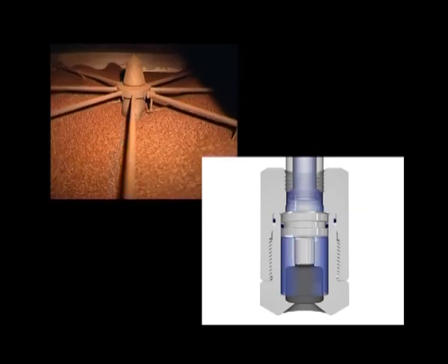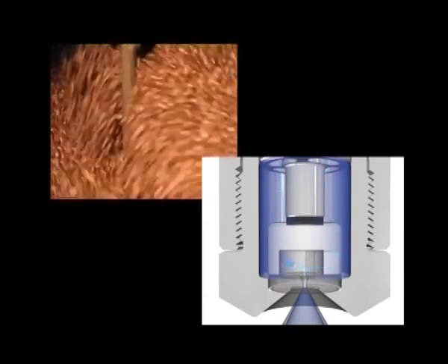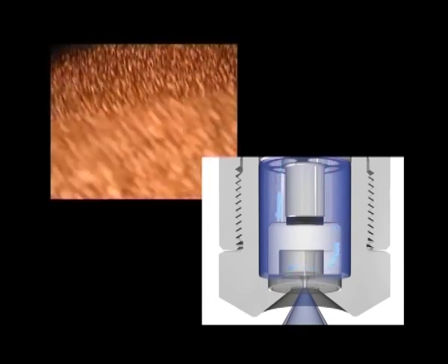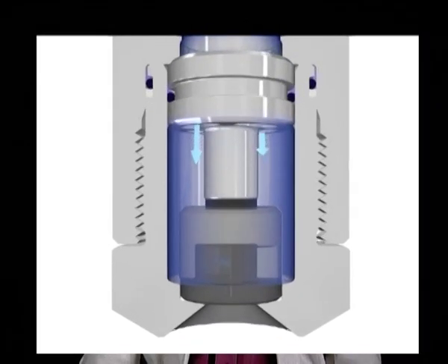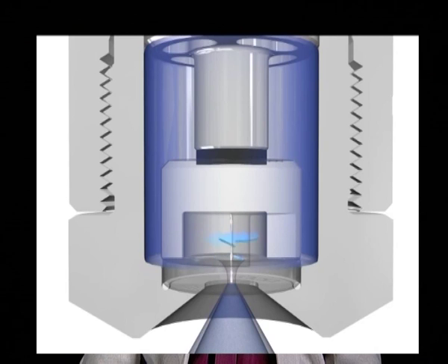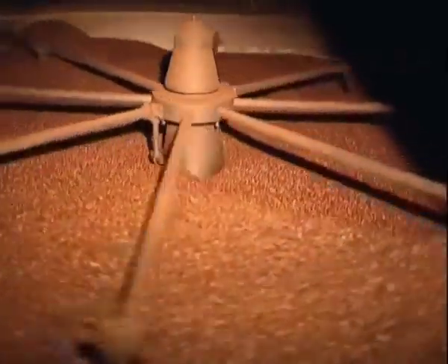In spray dryer, atomization can be achieved either by a nozzle or a rotary atomizer. The particle size will be of normal distribution in nozzle, whereas the particle size will be of uniform size in rotary atomizer.